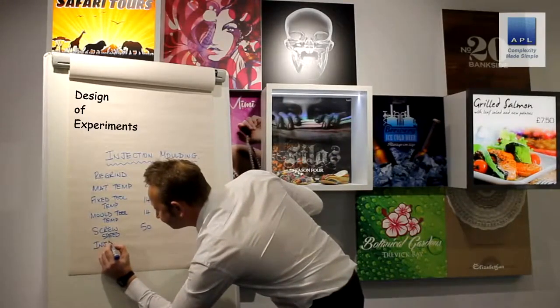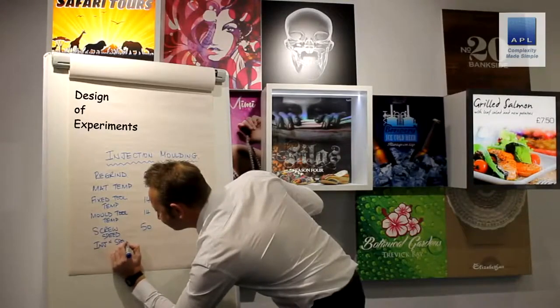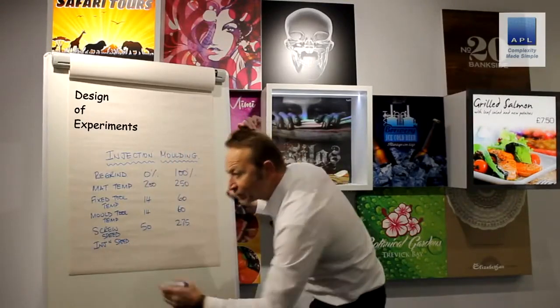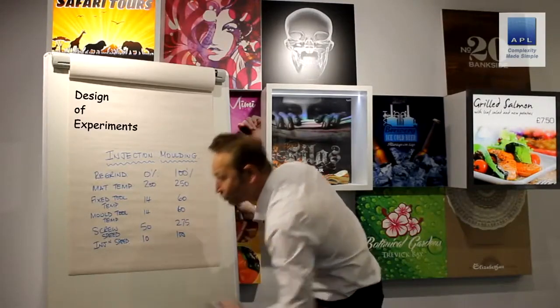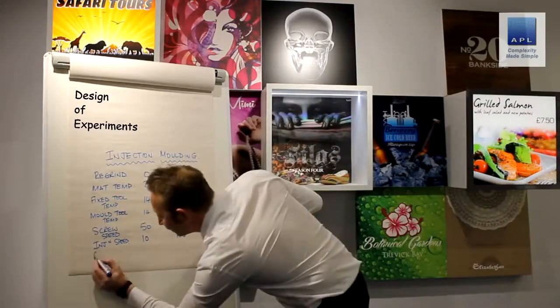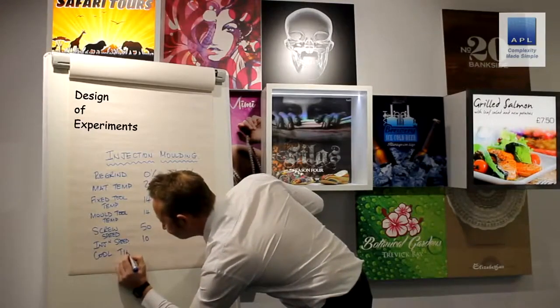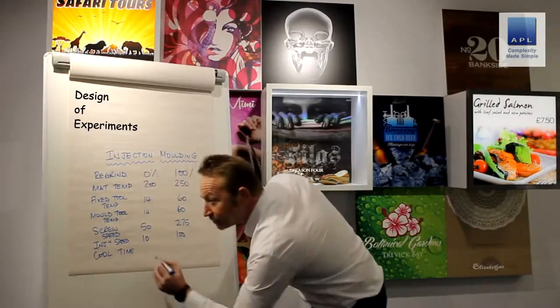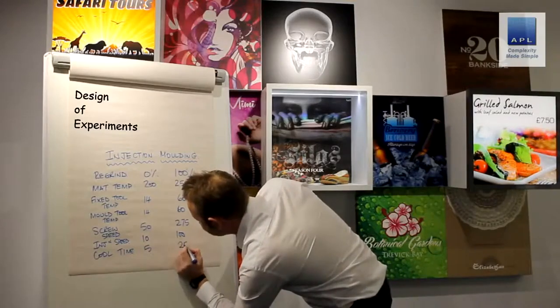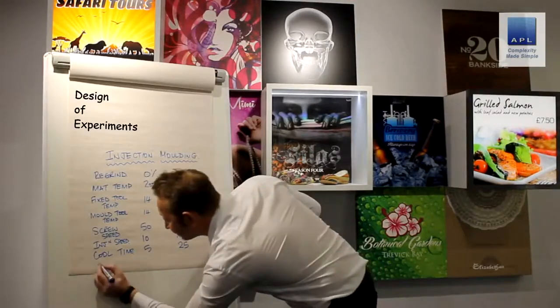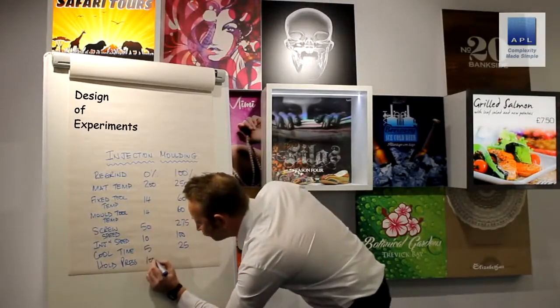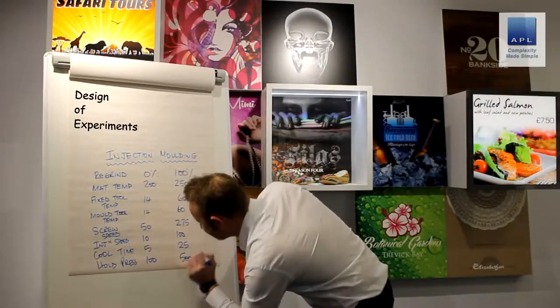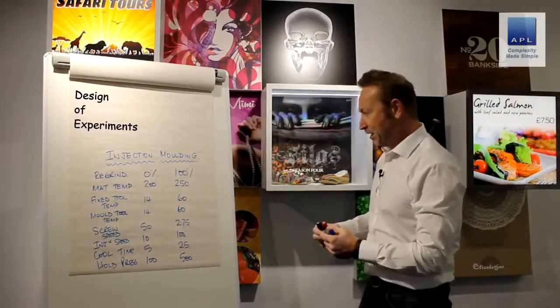Injection speed. That's going to go from 10 to 100. Cooling time is going to go from 5 to 25. And finally, hold pressure is going to go from 100 to 500.